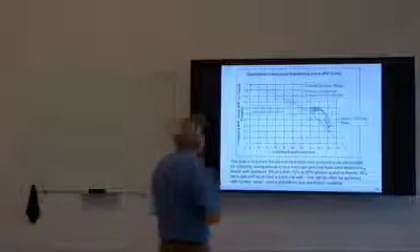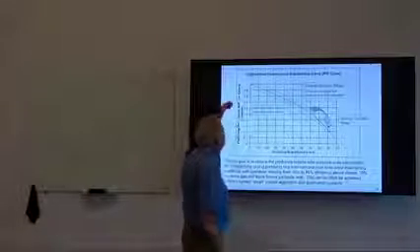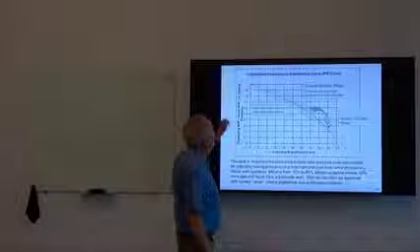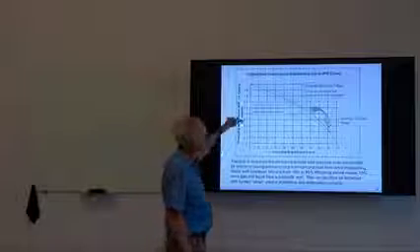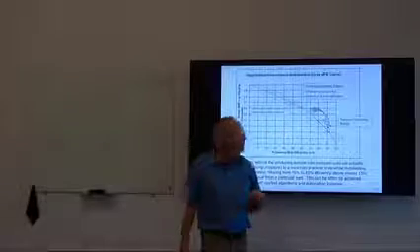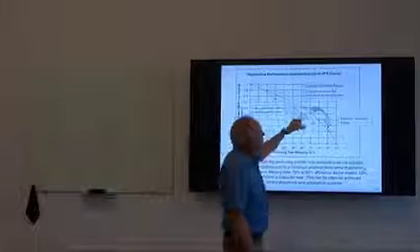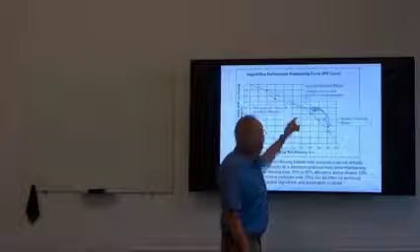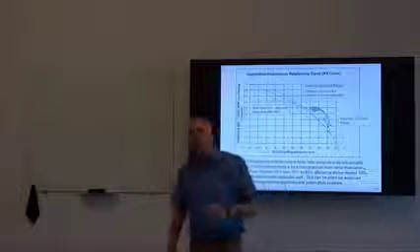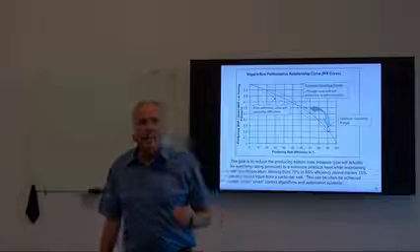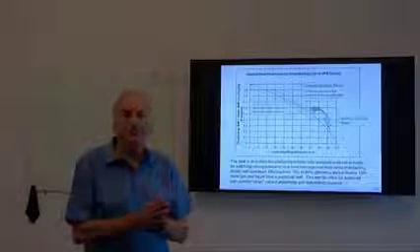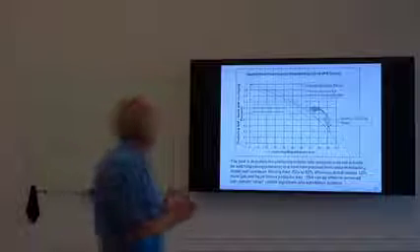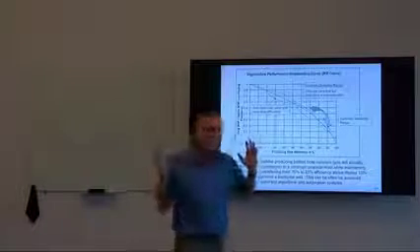If we are allowing this bottom hole pressure to build, and this is showing the pressure as a ratio of producing bottom hole pressure to the static pressure, it will be quite sub-optimized. But very often we also see a well running extremely well. The plunger is going up and down. It doesn't miss any trips. We're not breaking equipment or tearing up equipment. So it must be optimized.